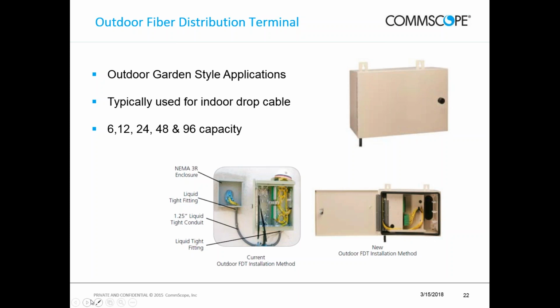If it's brownfield, now the whole building's closed up. Now we have to run all the drop cables exterior to the building and the residences, and then go underground or fix it to the side of the building. But in all cases, you have to punch a hole through the side of the wall to run the cable inside. Of course, there would be a NID box or something like that to place the RFOG micronode in as well, but you're going to have to blow a hole through the side of their customer's house in a brownfield environment to get that drop cable in.